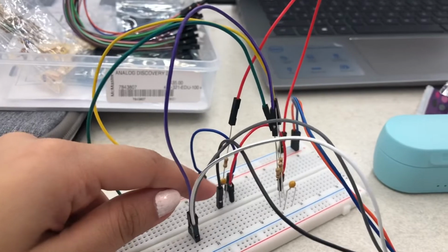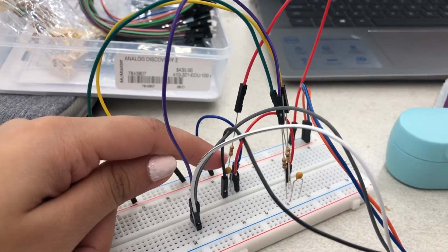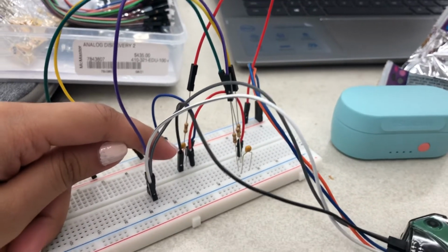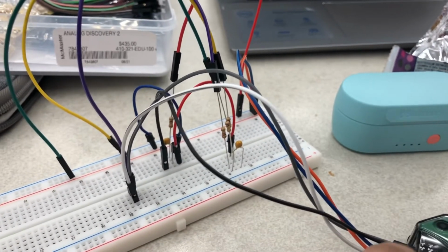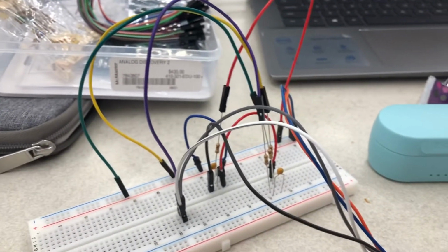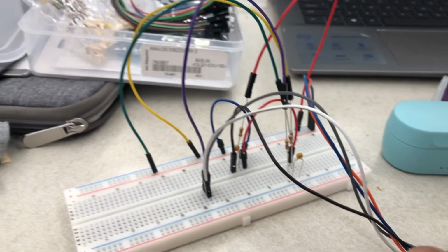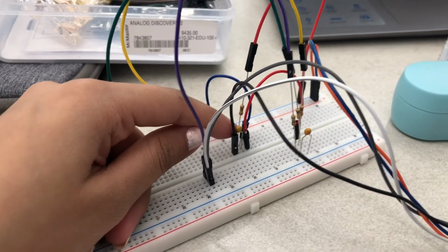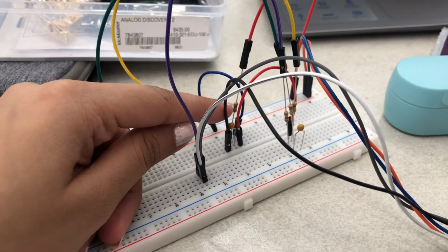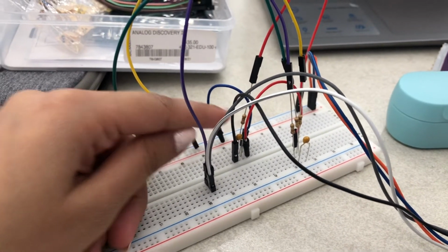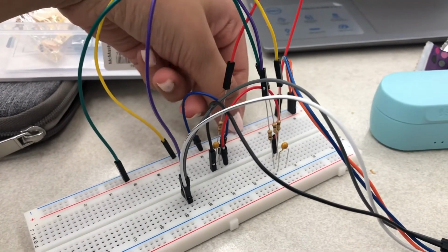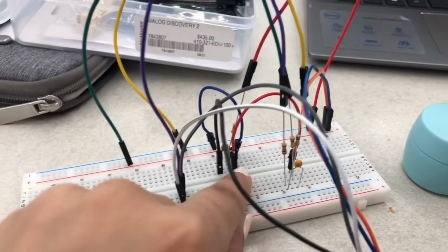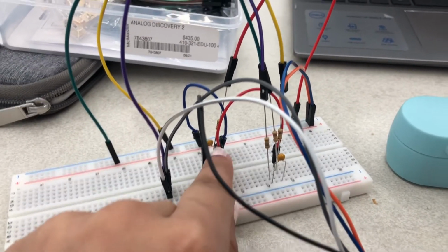The emitter node has 2 outputs. One of them is connected to this capacitor right here, which is 104, so 100 nF, and that is connected to this wire right here, which goes all the way to 2+. This is supposed to represent our V output so that we can measure it later. On the other end of this emitter, we have this resistor, which is 100 ohms, and it's supposed to be our RL. It goes all the way to this end over here, which is then connected to our negative 5 volts as mentioned earlier.